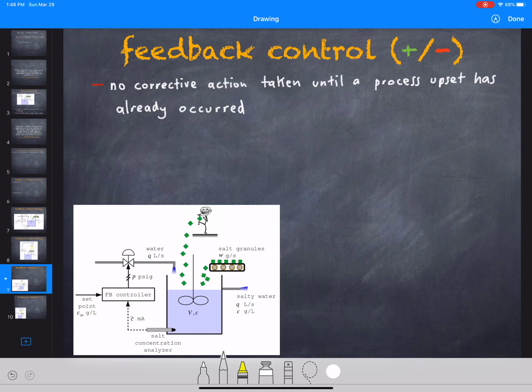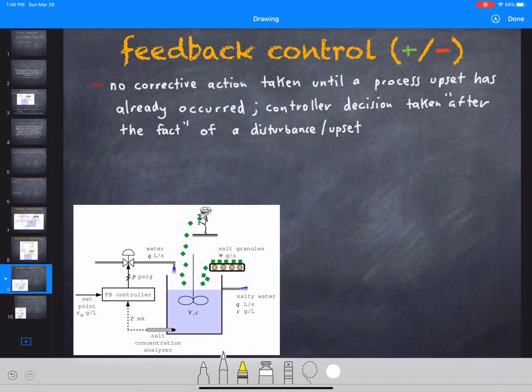And that's because you're measuring the control variable, and you'll never know. Basically, the only time you can take action is whenever you see a deviation from the set point. And so controller decisions are taken after the fact of a disturbance upset. That is, the concentration of salt has to deviate from its set point before action is taken.